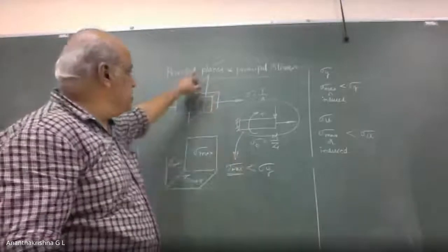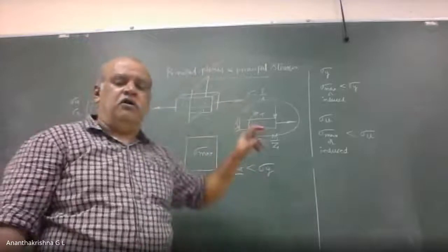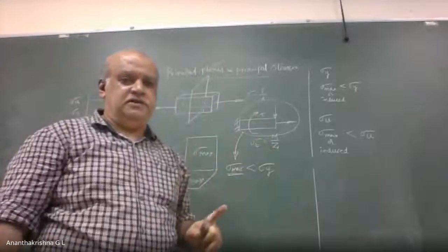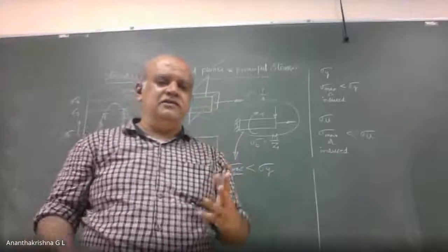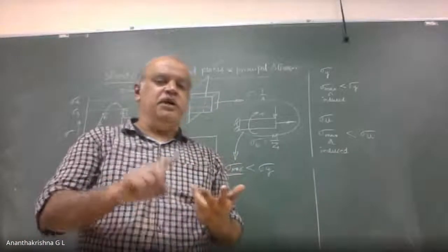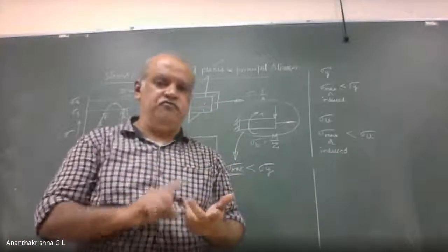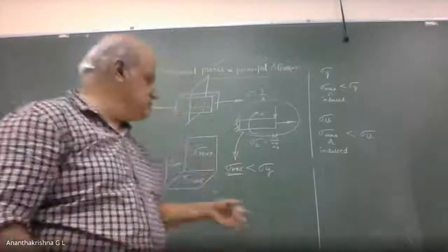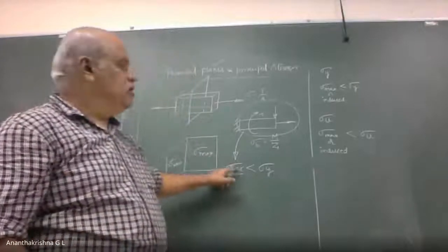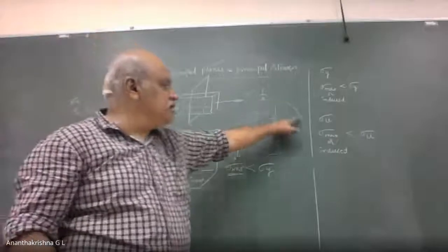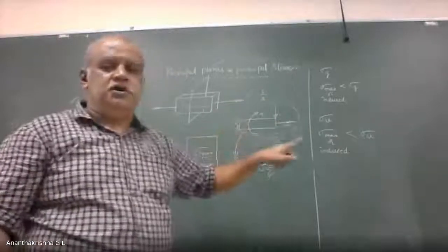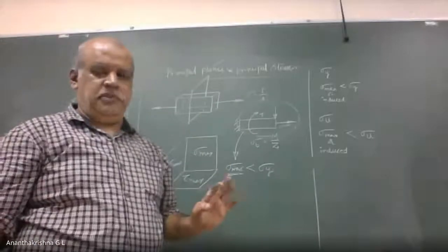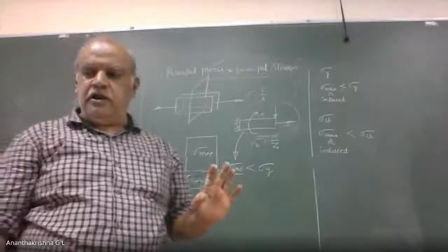And the planes which have got zero shear stress are called principal planes. Are you with me? So the total essence of learning principal planes and principal stresses is to find out the maximum stress induced in a member which is subjected to a combination of loads, which can be axial, bending, and torsion together. Are you there with me? Yes, sir.